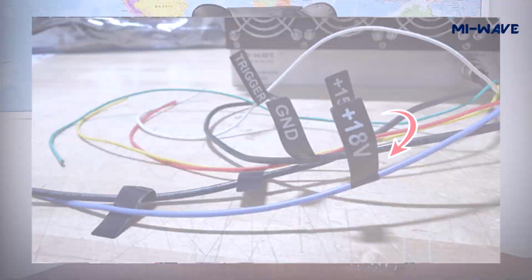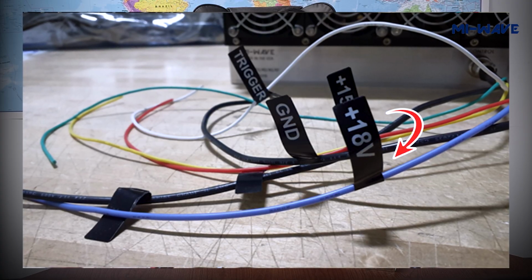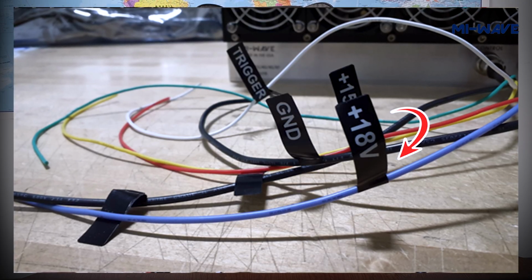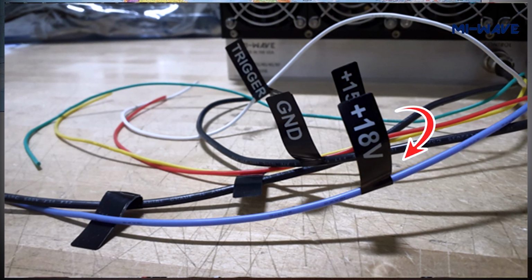The next connection is the 18 volts DC power supply. The 18 volts rail is used for controlling the synthesizer. If separate power supplies are used for 15 volts and 18 volt rails, the ground terminals of both power supplies must be connected together before connecting them to the synthesizer. This ensures that both supplies share the same reference ground.